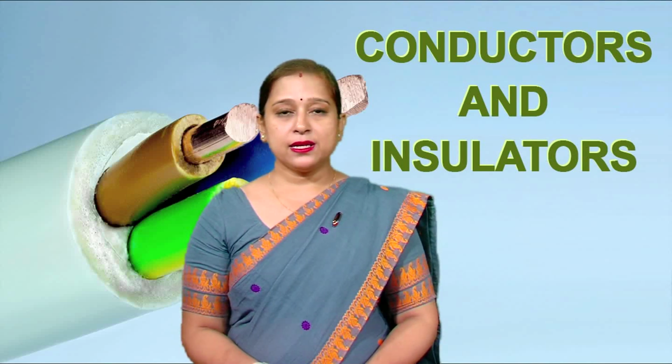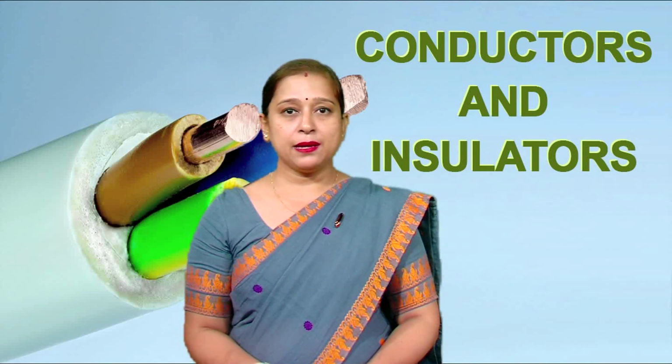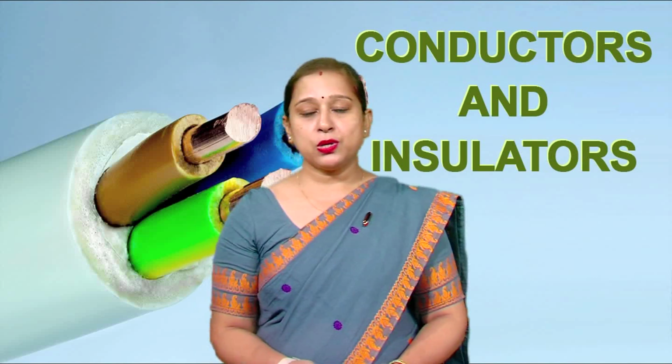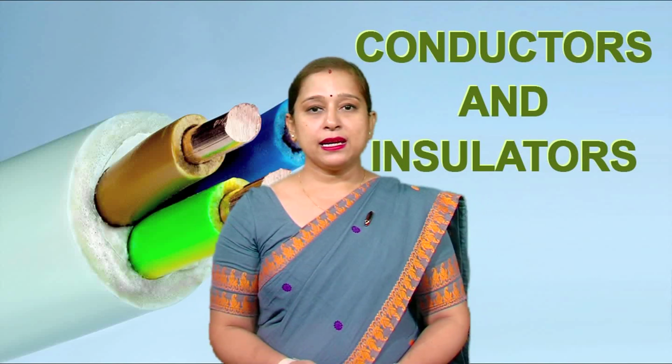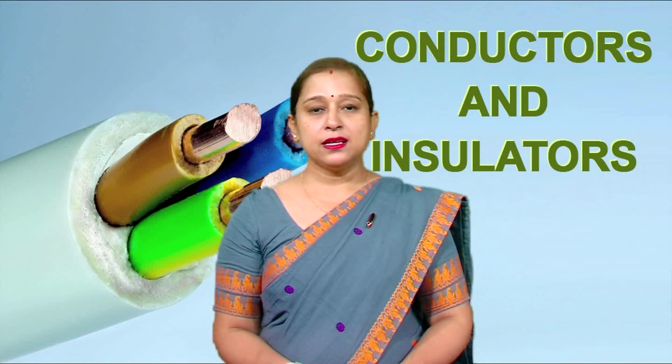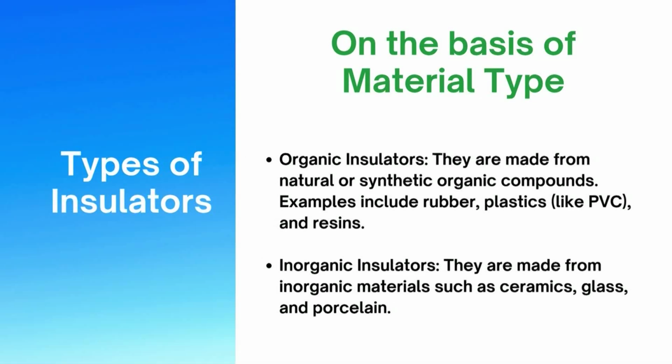Electrical insulators can be classified into different types. On the basis of the type of material we are using, the insulators can be classified as organic insulators. The organic insulators are made from natural or synthetic organic compounds, for example, rubber, plastic, resin, etc. They can also be classified as inorganic insulators, which are made from inorganic materials such as ceramics, glass, and porcelain.